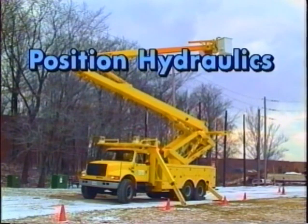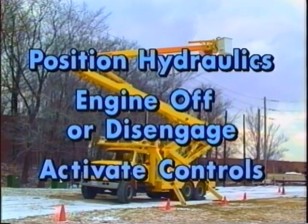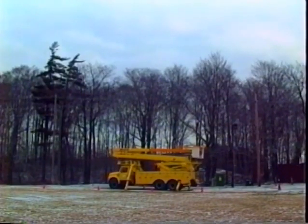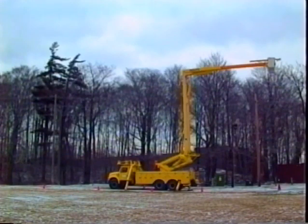Position the hydraulics. Turn off the engine or disengage the boom. Activate the controls. On an aerial device, you check the holding valves with the boom in 3 different positions. Here is position 1. The upper boom is at least a foot off the rest. When you activate the controls, you should not see the cylinder move. Now test the holding valves with the boom in this position. And then repeat the tests with the boom as shown here.